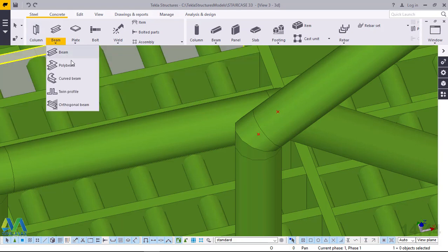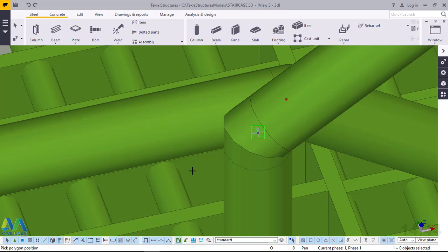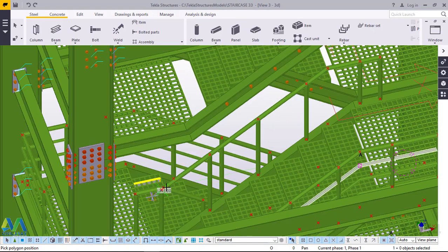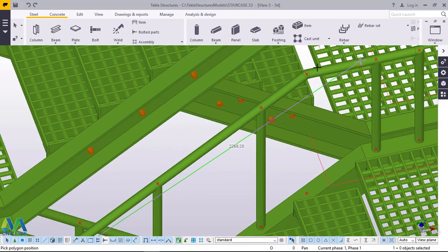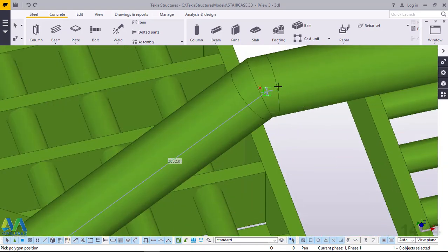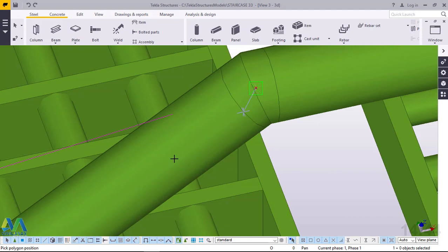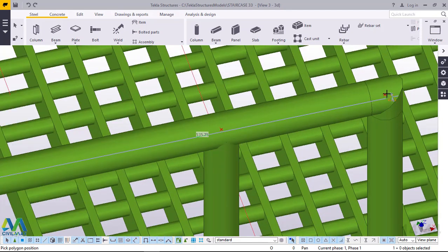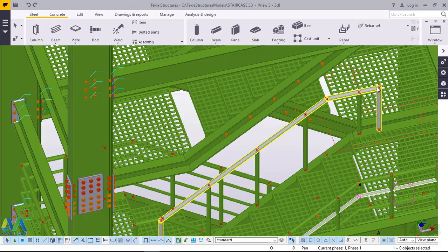I'll come to that spot and come to polybeam, and I'll snap on this spot. I'll zoom it out, and I'll snap on this spot right here, on that spot right there, and I'll come all the way and wind it here and press my middle button on the mouse to terminate it at that point.